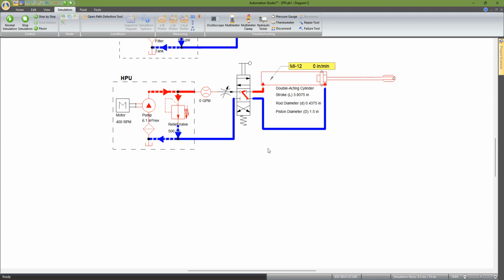If I go now to the closed position, this fluid cannot release the pressure because it was never connected to the tank throughout the stroke, okay? But this one was always connected to the tank. So even though you disconnect that, the fluid inside that is now trapped is still in low pressure.